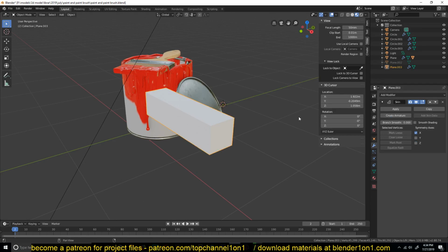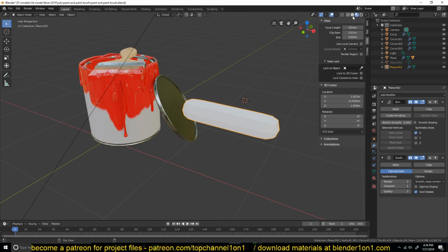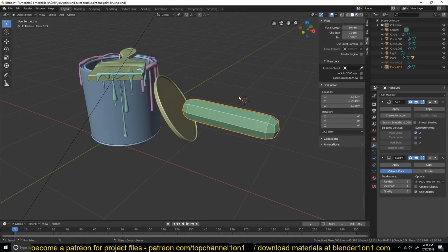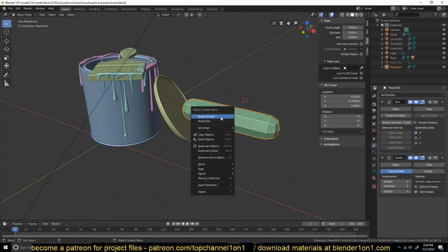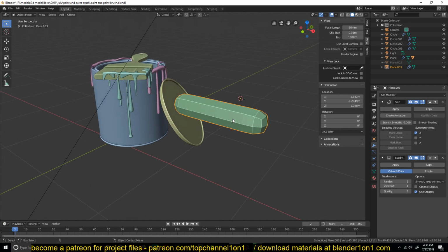So to make this smooth, we are going to add a subdivision surface modifier like this, and later we'll be applying smooth shade to this, but I don't think it works when you have the skin modifier. It doesn't apply. When I tried it, I had to apply the skin modifier for that to work. So if you try that and it doesn't work, I just know that it didn't work for me as well.